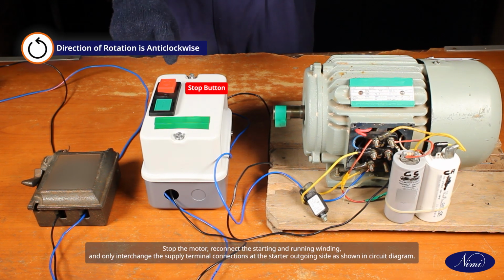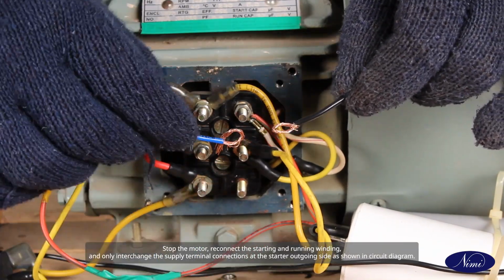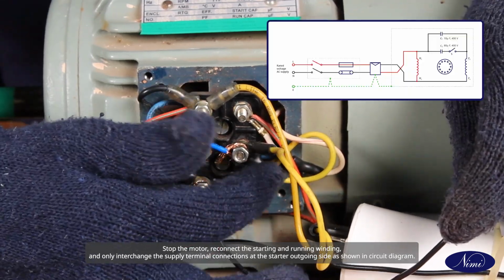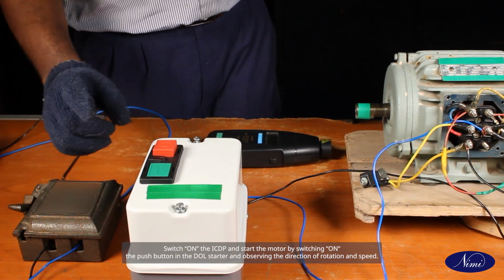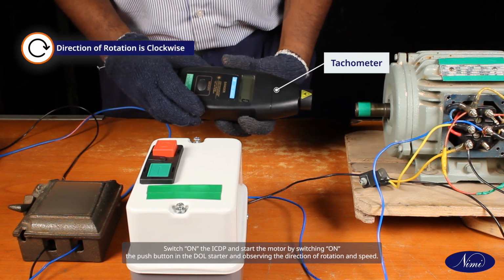of rotation. Stop the motor, reconnect the starting and running winding and only interchange the supply terminal connections at the starter outgoing side as shown in the circuit diagram. Switch on the ICDP and start the motor by switching on the push button in the DOL starter and observing the direction of rotation and speed.